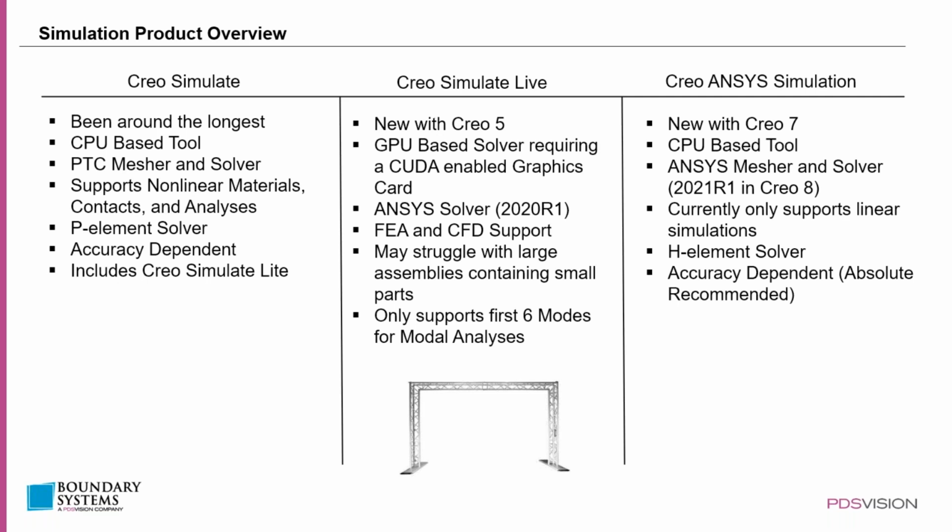The disadvantages are, in some situations, the accuracy will be lower. That'll include thermal analyses. It'll include structural analyses where you're worried about max stress, especially in large assemblies with small components. So you do have, in theory, slightly less accurate results, but if you're looking for a quick ballpark, it's going to be very, very, very useful.